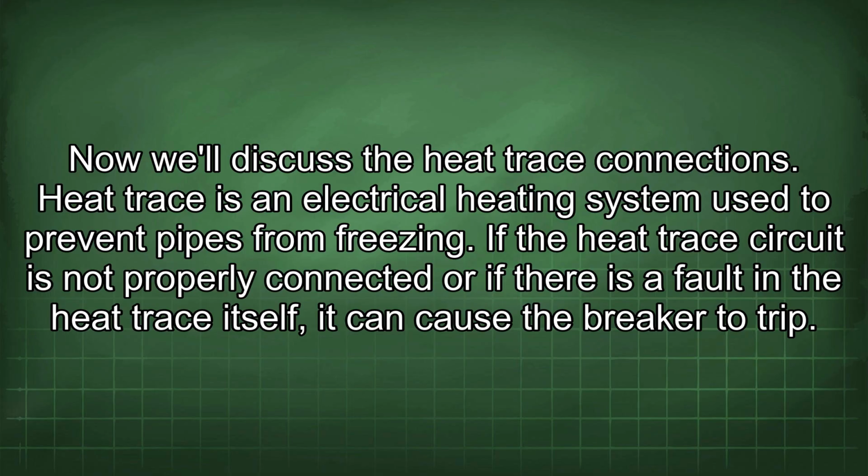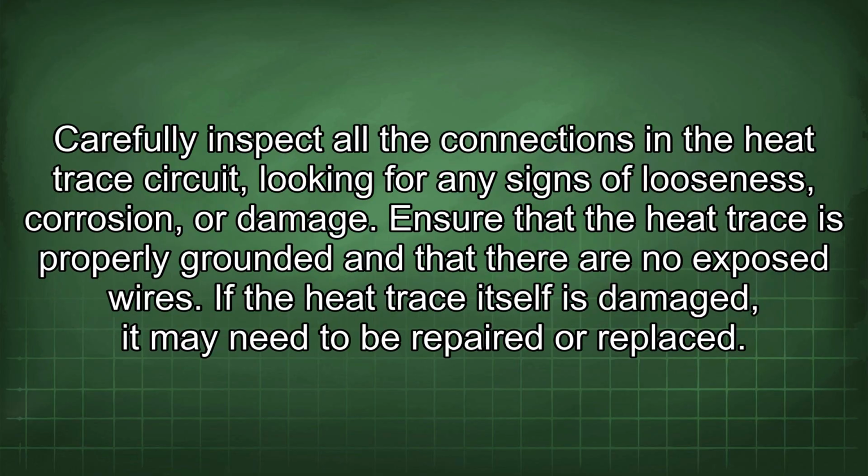Now we'll discuss the heat trace connections. Heat trace is an electrical heating system used to prevent pipes from freezing. If the heat trace circuit is not properly connected or if there is a fault in the heat trace itself, it can cause the breaker to trip. Carefully inspect all the connections in the heat trace circuit, looking for any signs of looseness, corrosion, or damage. Ensure that the heat trace is properly grounded and that there are no exposed wires. If the heat trace itself is damaged, it may need to be repaired or replaced.